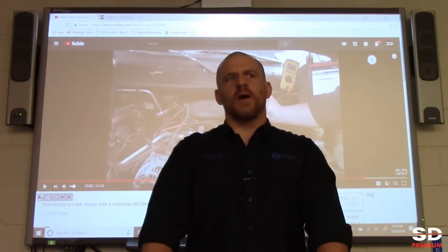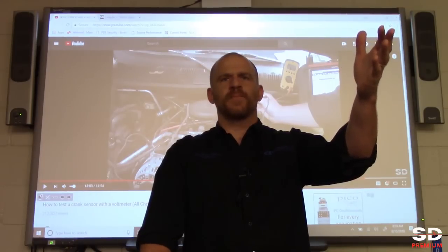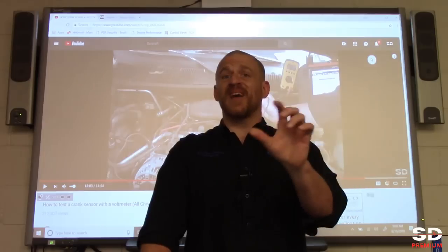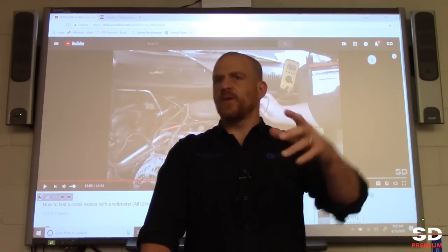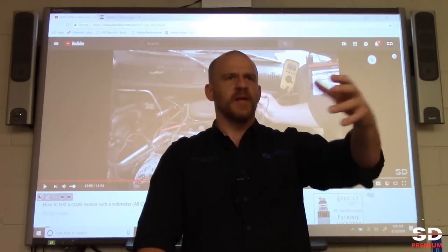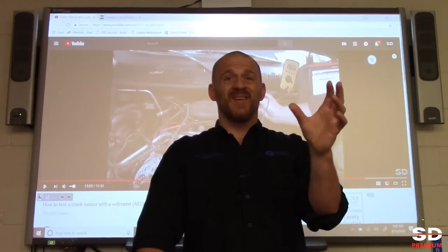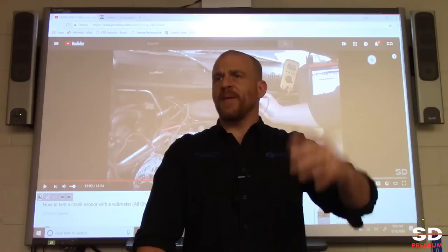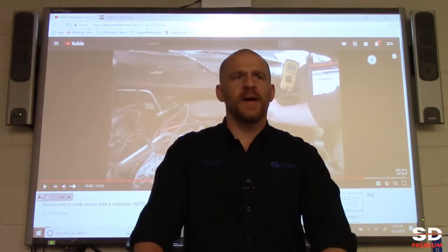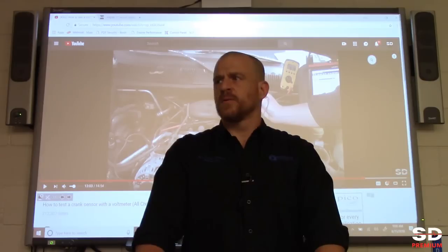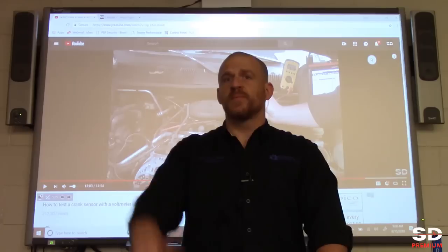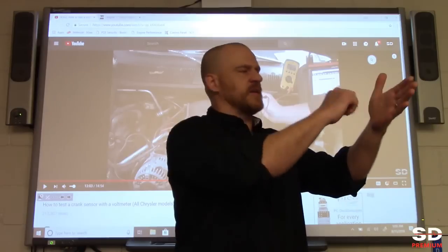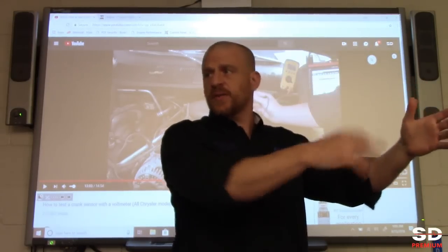I was thinking one, Bryce had mentioned cruise control earlier. If you were checking a cruise control, say, set or accel switch. You guys know what I'm talking about? You have your accel, then you have your decel or coast, right? Let's say that your cruise control set button wasn't working and you're looking at troubleshooting it and you're going to do a bypass test. What are you looking at to know if the bypass test worked? See if it says on and off. On what? Like scan tool. Scan tool. Yep. On a data PID on the scan tool, I'm looking at cruise control. It says set and it says off. I do take my test light, touch on the circuit. What does it do?